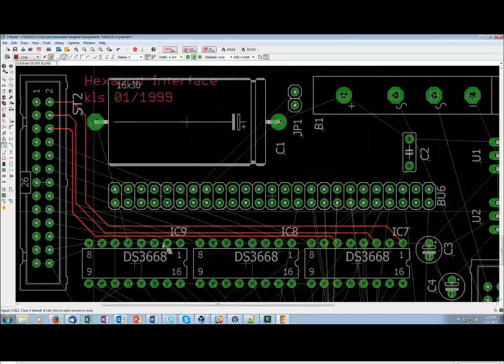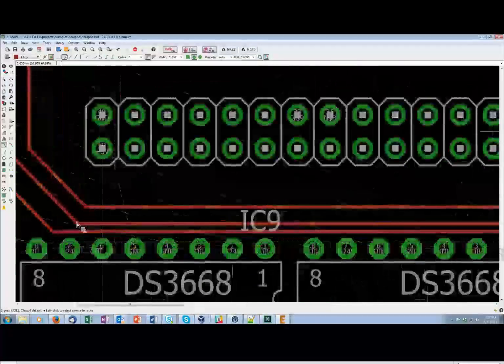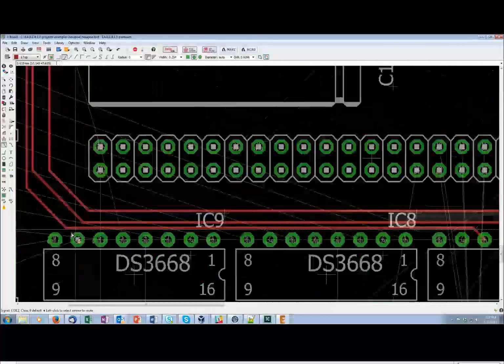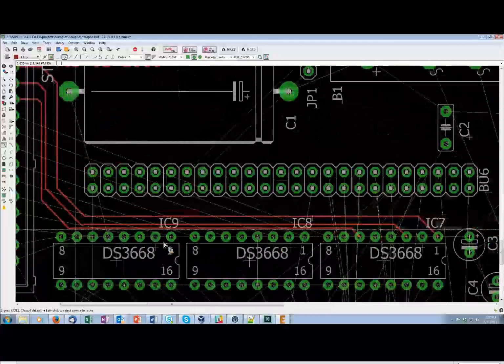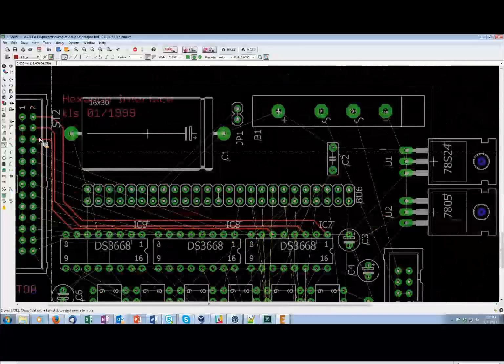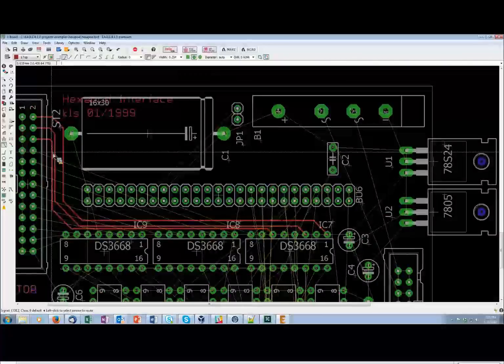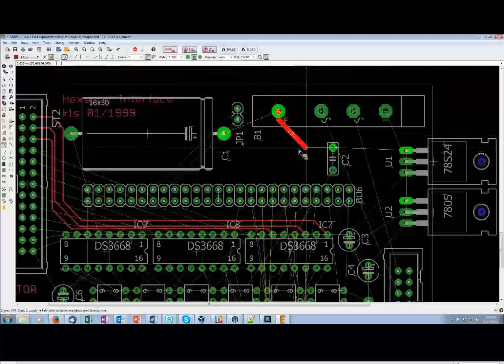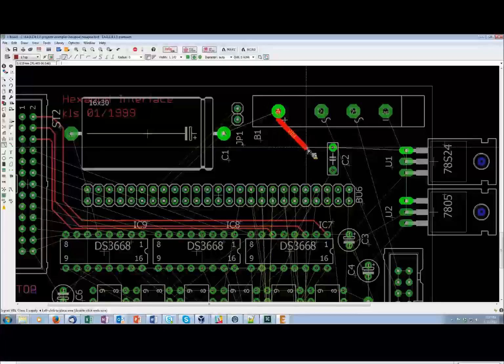Now what it's doing this whole time is it respects the clearances. So it's respecting what we set up in the DRC. You don't have to worry about these creating issues when you run the DRC. Okay? And let's even observe that with the thick traces of the power nets. If we go over here, notice we have a really nice big trace. Go ahead and take it to there. Take it to there. Okay?